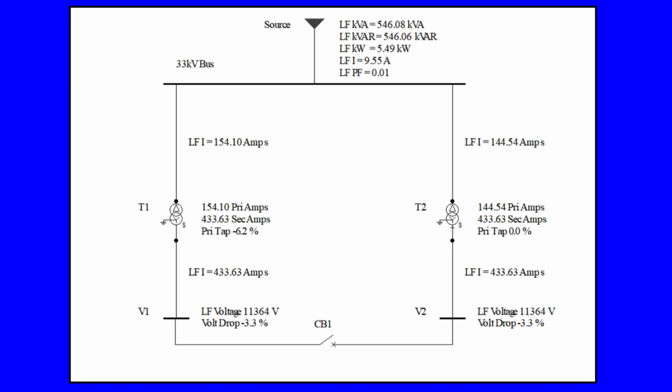Interesting to note also that a 5-tap difference between the transformers can lead to circulating current equivalent to full load current of the transformers. Hence, overloading is a very real danger with circulating current, even though the circulating current is highly inductive, whilst load current usually has a high power factor. In other words, the addition of circulating current to load current is not a simple algebraic addition, but an addition of complex phasors. Hence, in a nutshell, there is a limit as to the use of transformers on different taps to regulate network voltage with low loading.